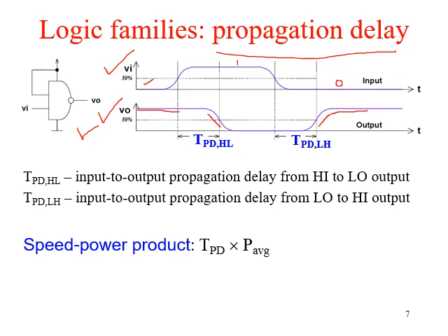What we do is take the 50% value for both the waveforms. Suppose this particular amplitude is 1 unit, then we take a line at 0.5. This is the 50% line. Where the 50% line intersects this curve, we mark this point. Again, we get another point. Similarly, we take the 50% points for the output waveform. Now we take the difference of time between, say, this point 1 and this output point 2, and this value is referred to as TPD-HL. Again, we get another point for input and one for output. We take the time difference for these, and this is referred to as TPD-LH.